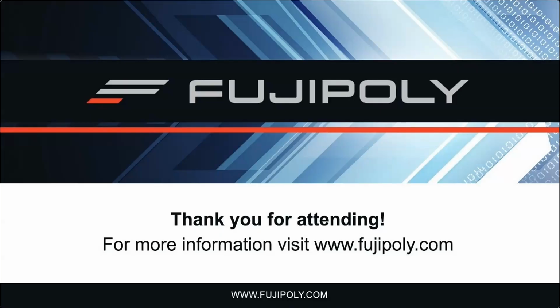One possible offering that we have is a newly developed material. I don't believe it's on the website yet, but it's a cleaning putty. So again, after you wipe the grease off, and then you still have some residue remaining, just try to apply this cleaning putty over that area. It's a pretty soft, putty type of material. So you can apply a little bit of pressure, and make sure that you're careful around your components, and then just peel it off, and it should start to remove some of that grease. You might have to do multiple passes even with that. But if you're interested in some more information, please feel free to reach out to us on the website on that product.